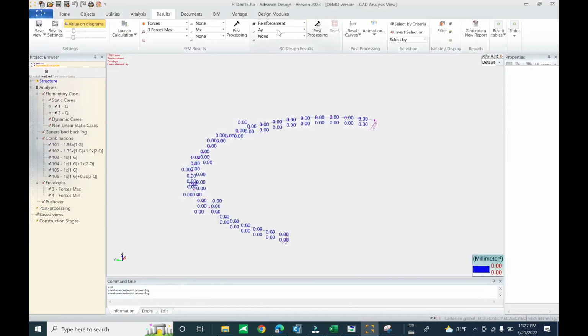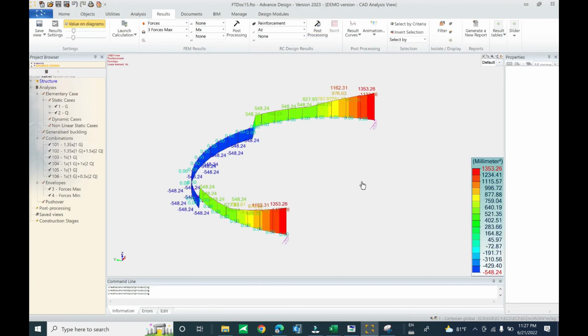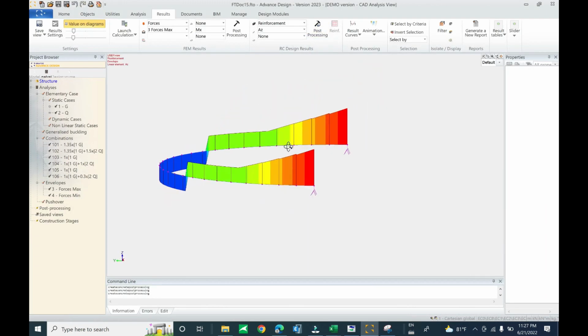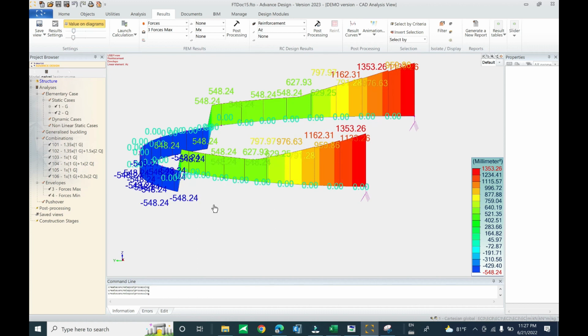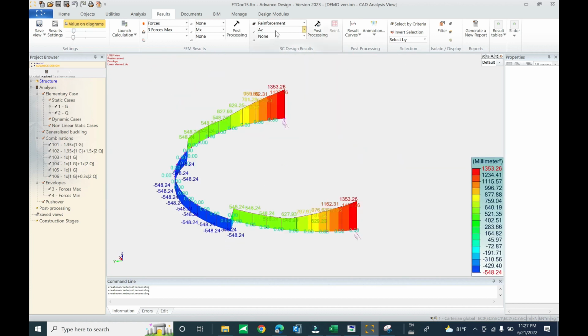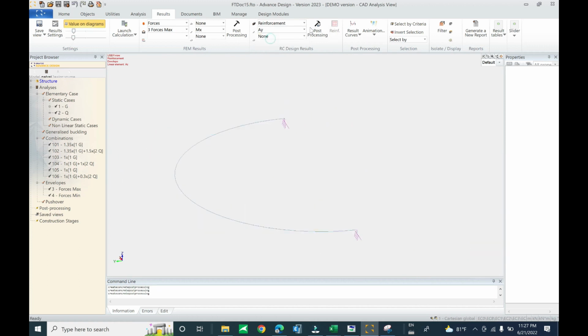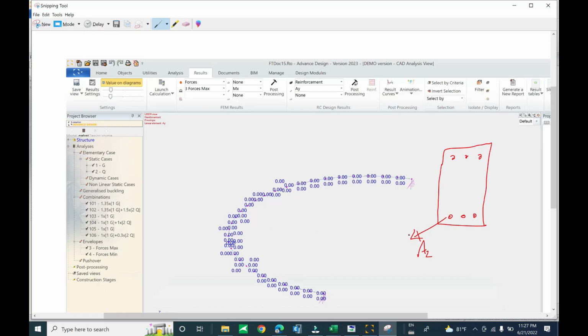Okay, when you show the AZ, you can check AZ at the top and at the bottom. And AY is the reinforcement in this direction. What indicates reinforcement in this direction is not required. No need. We need only reinforcement AZ, top and bottom.